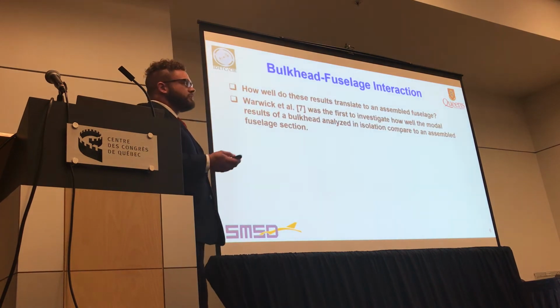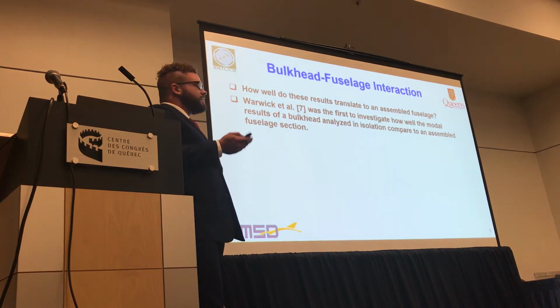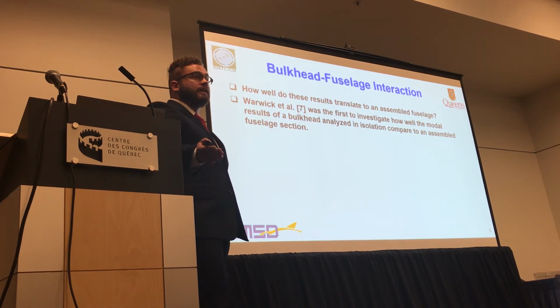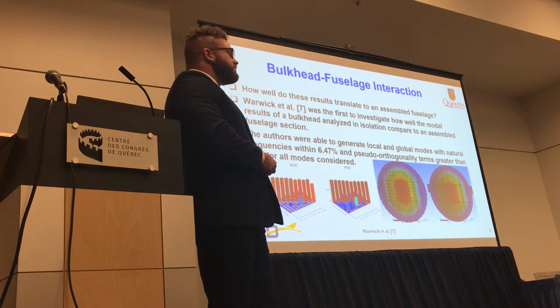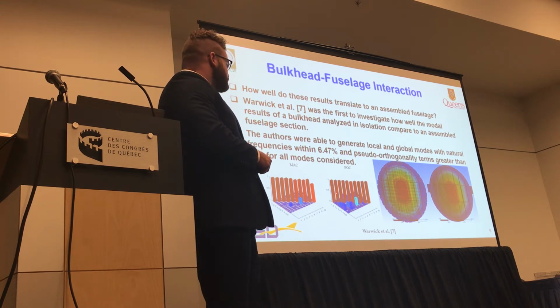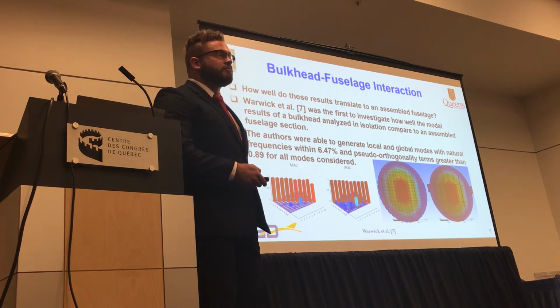A recent journal publication of mine that's currently under review was the first to investigate how well the modal parameters of the bulkhead analyzed in isolation compare to the bulkhead analyzed in a fuselage. We were able to show that qualitatively the mode shapes agree quite well between the bulkhead analyzed in isolation and in a fuselage. We can also see that the MAC and pseudo-orthogonality checks gave quite good results as well, and the natural frequencies agreed within about 6.5% on average.